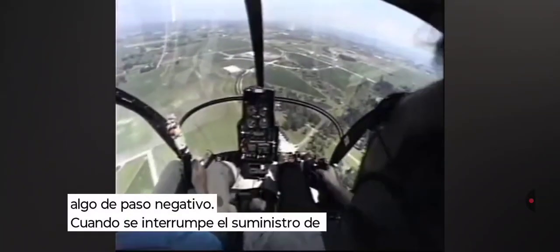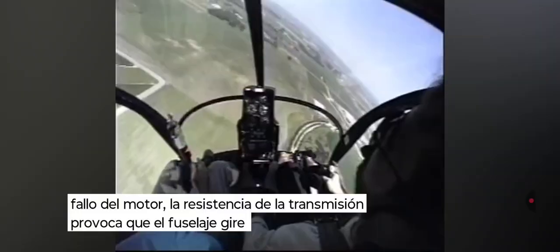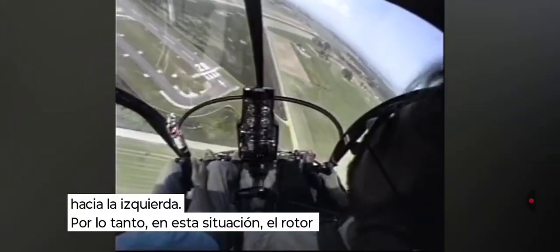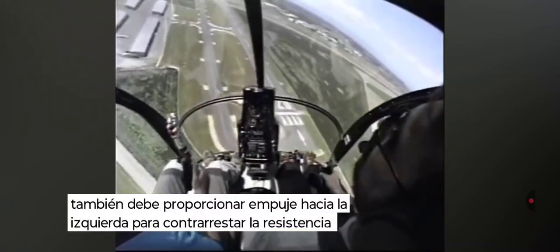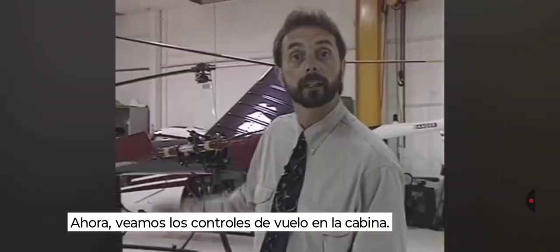When power is removed from the main rotor, as in the event of an engine failure, the drag of the transmission will cause the fuselage to yaw in the same direction as the main rotor, that is, to the left. So in this situation, the tail rotor must also be able to provide thrust to the left to counteract the drag of the transmission during autorotation. Now let's go into the cockpit to take a look at the flight controls.